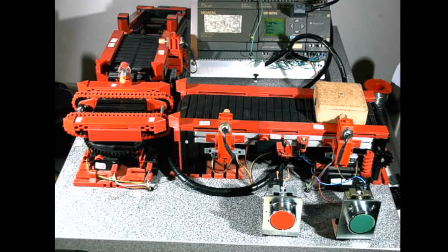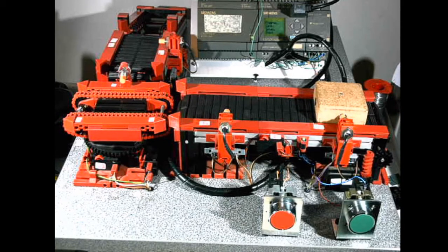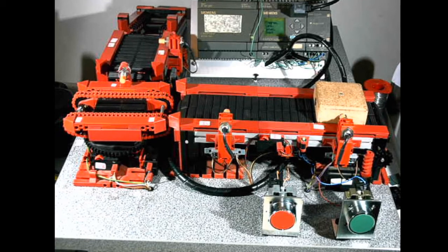We need to validate whether they are normally closed or normally open. And the other one, there is I4, and then the last one is I7, which is an infrared. And then all these are metallic. They cannot sense anything except metallic sensor. These ones are metallic, and we have two mechanical switches which you actuate or activate by pressing them. They're more like push buttons with a spring return.